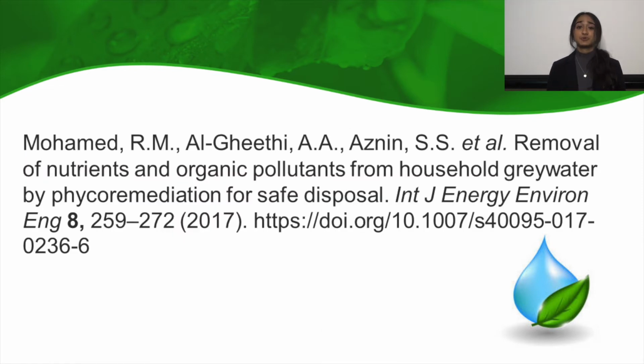Gray water purification requirements significantly vary based on the source itself. For example, recycling kitchen water is the most difficult task due to the very high levels of organic materials and solids. Most studies in the literature, including ones from Malaysia, consider gray water as the water from all the usage points combined, except for black water, which is the water from toilet flushing.